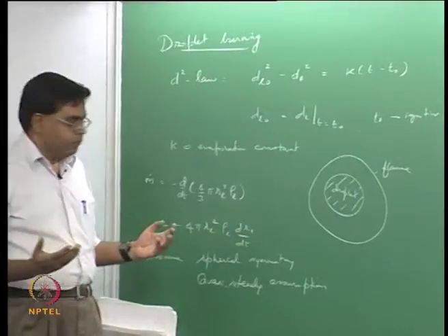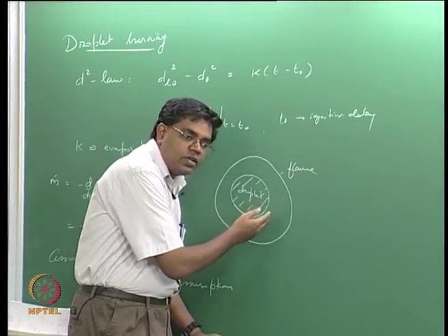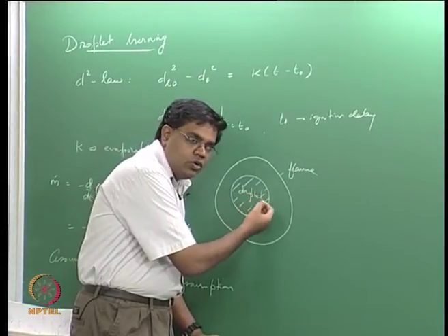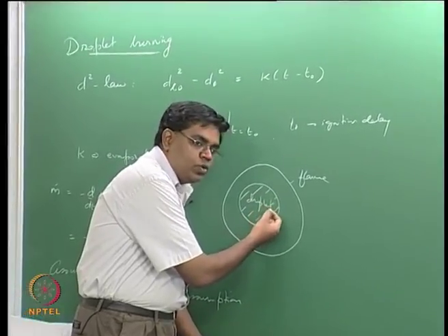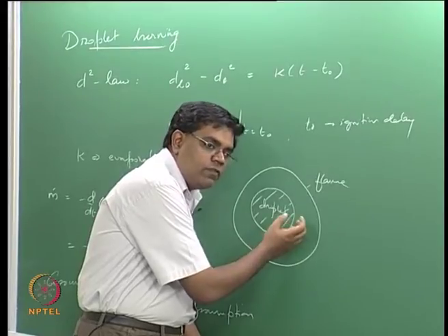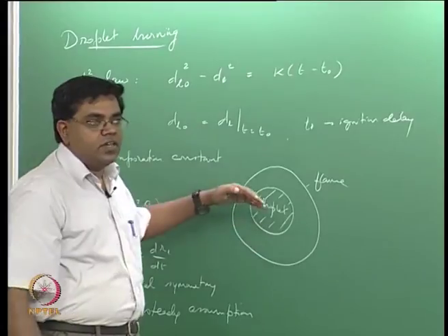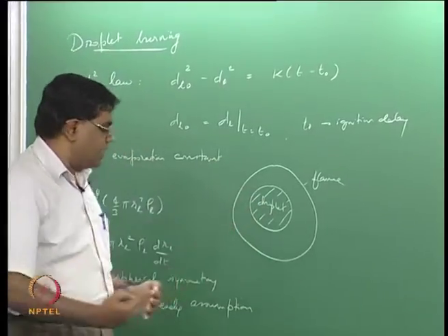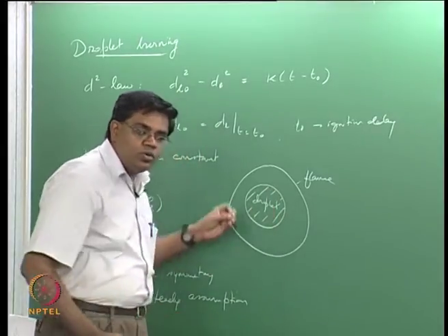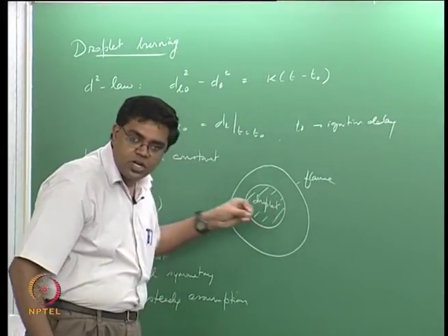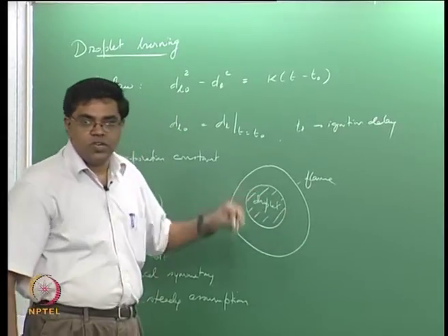So what? The answer is we need to look at mass conservation across the interface. For a unit mass per volume of liquid to evaporate will give rise to a much lower density, which means as the surface recedes inward, it is going to put out gas that has to move radially outward at a significantly larger rate.